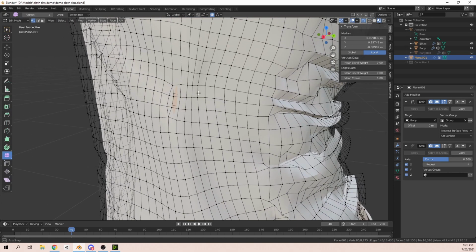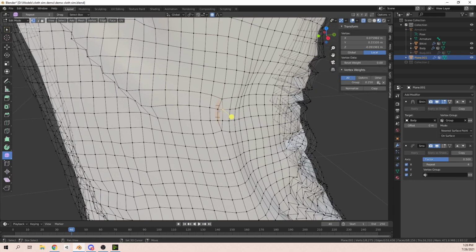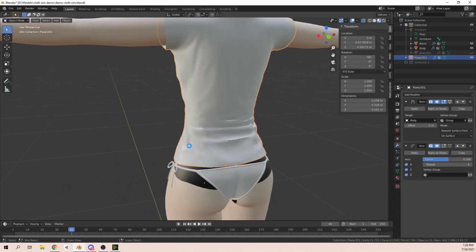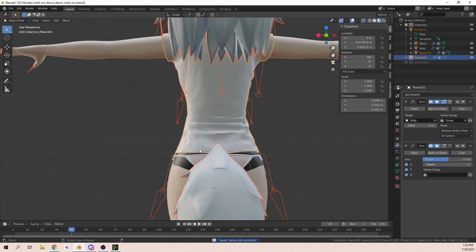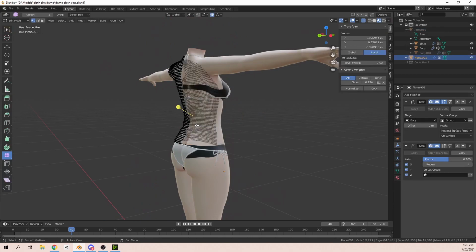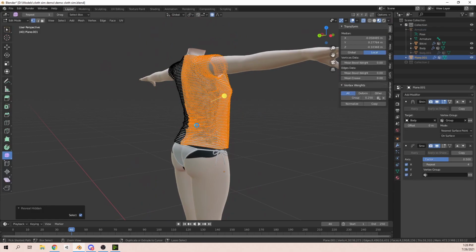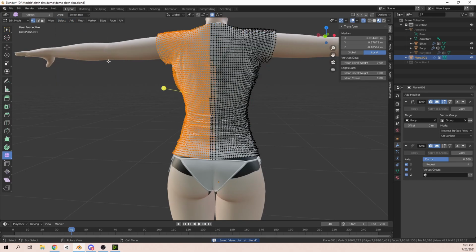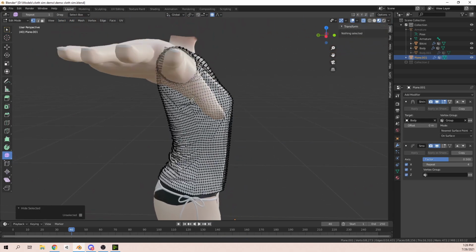You can see here, there's totally some verts that didn't get merged. So I'm going to merge at the center. Boom. I'm going to save. I'm going to unhide. Well, I unhid the wrong thing. I need to go back to this and press Alt H to unhide. I'm going to select, invert my selection, and just hide that.